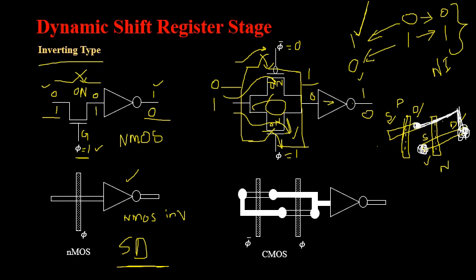So similarly this source as well as this source has to be connected together. So this is your P type of diffusion that has to get connected with N type. So I will be using a contact cut over here and I am connecting it with the metal layer. So this is what is shown over here. So hope you understood how to draw this diagram. So that is how we have drawn the diagram here.